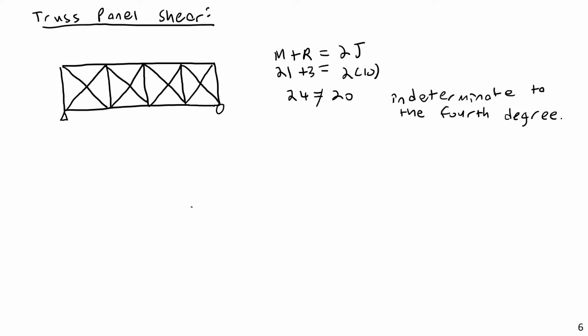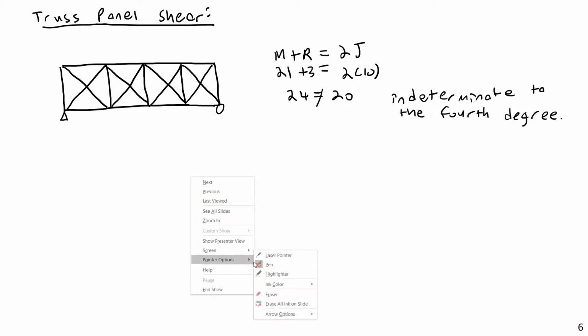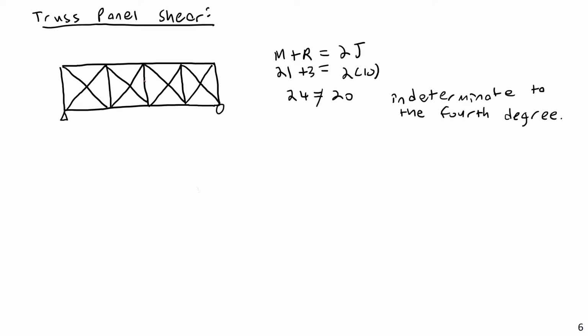However, what do I do to get my initial design to feed into the computer? Well, I can use approximate methods. And using just those assumptions, looking at this truss, I can see 4 easy equations that I can get to immediately make this a determinate system, or at least something that is determinate enough to get an initial design. So for example, let's say that there's a load on here, and let's apply a 30 kip load here, and that's too boring. Let's say there's a 30 kip load here.